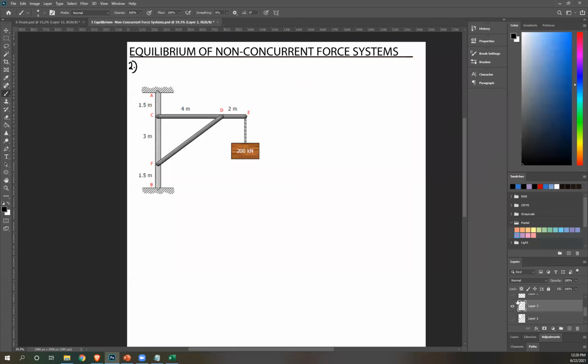So if we were to draw that, it's gonna look something like this. Downward force, and then we need to convert that to a point load. So here. Okay, so I don't have to draw that anymore. We can just compute for the point loads. So let's create a variable for each point load. Since all of these are rectangular distributed loads, since it's area that's uniform, the position of your point load is going to be at the middle of your span. So for 6, the middle is at 3. So it's somewhere here.